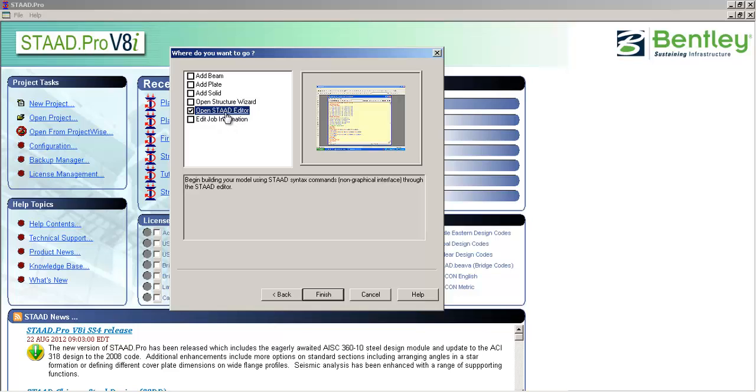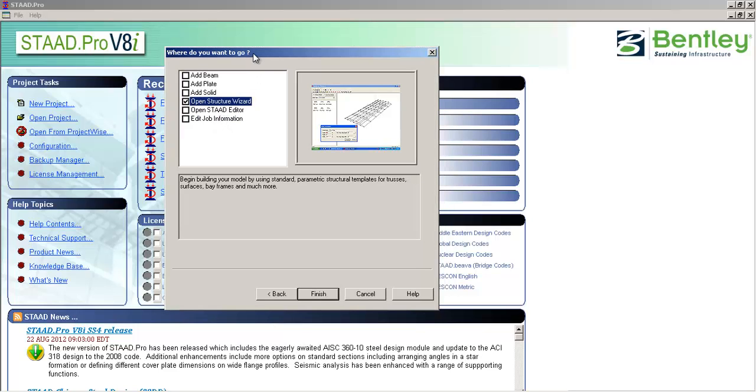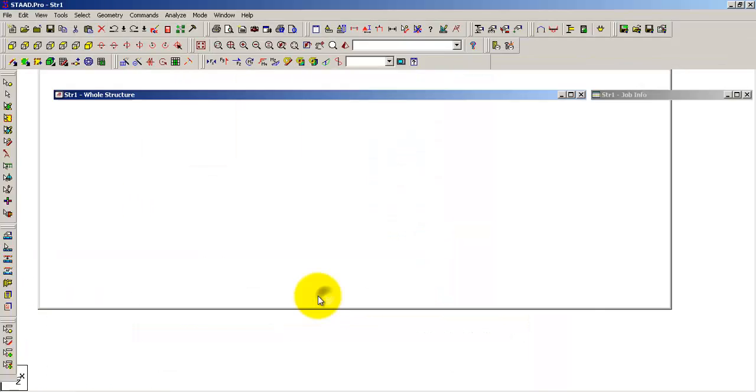You can see the picture in this. It helps in merging and importing the models given in this predefined models box below, built into the library. You can see the add beam option. We can add any structure which you have built in AutoCAD or any irregular shapes. While in structure wizard, we have the software merge a predefined model. Here it is given. Here it is a stadium roof which the user is importing. So we would use the add beam option and click finish.